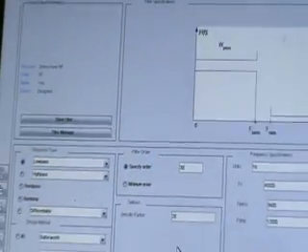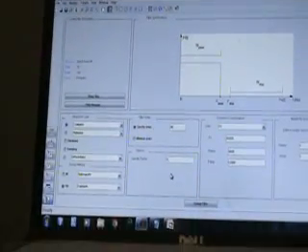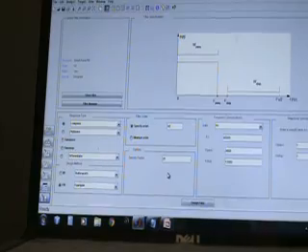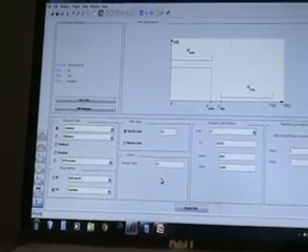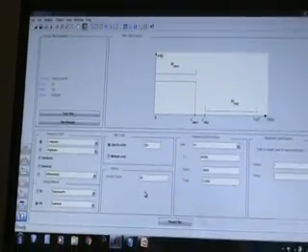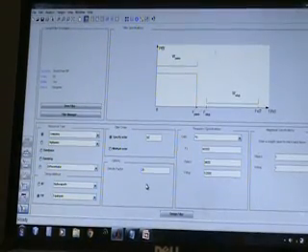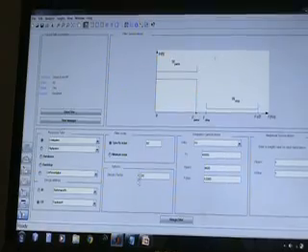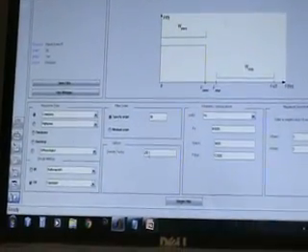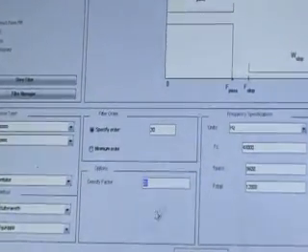then we can enter 30, and the density factor option controls the density of the frequency grid. Increasing the value creates a filter which more closely approximates an ideal equiripple filter, but more time is required as computation increases. So we'll leave this as 20, which is the most optimal value.